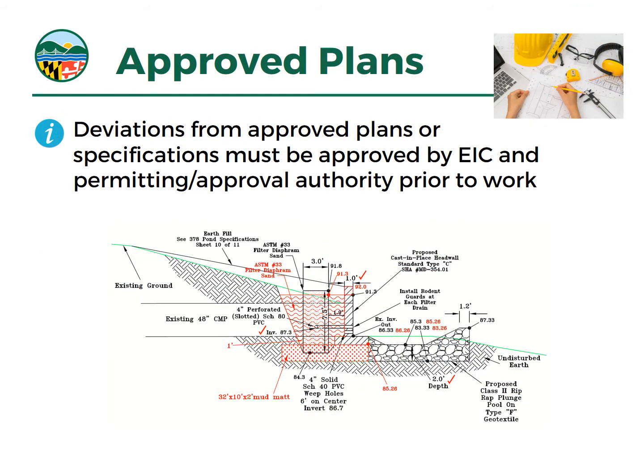All right, I want to talk about the approved plan sets as well. When we issue a dam safety permit, the permit incorporates by reference the approved plan set. And it's important because sometimes plan sets might change over time. Maybe we approved something with a May 1 date, but then some changes were made because of, let's say, a stormwater management issue or erosion and sediment control issue. Those changes may be inconsequential, but they might be consequential. So it's important to work from the approved plan set, and if changes need to be made to that approved plan set, we can make that happen.